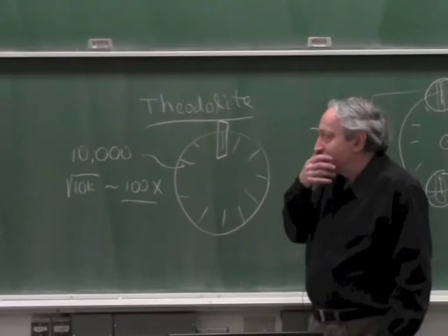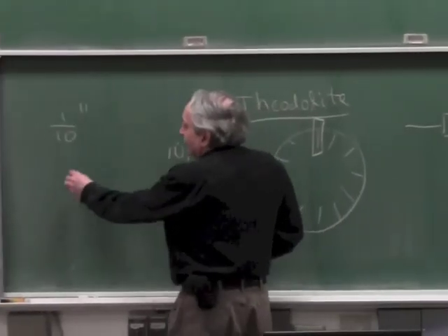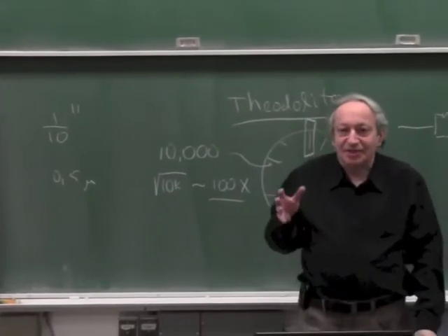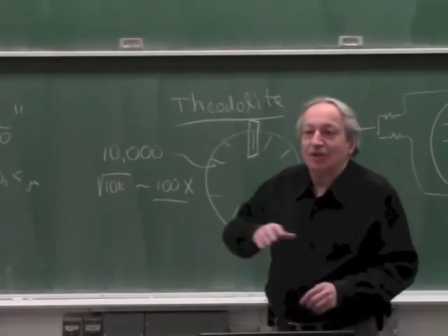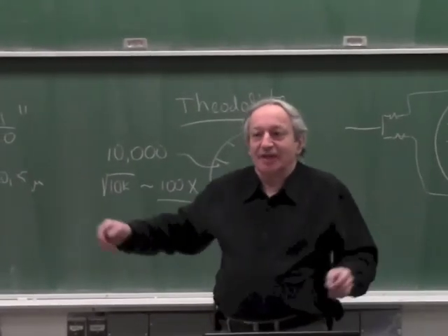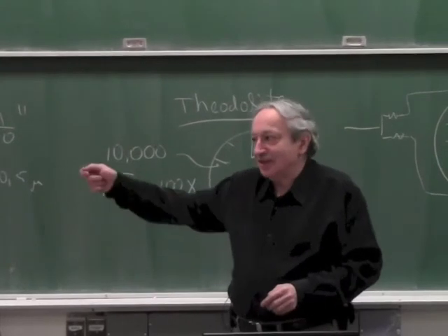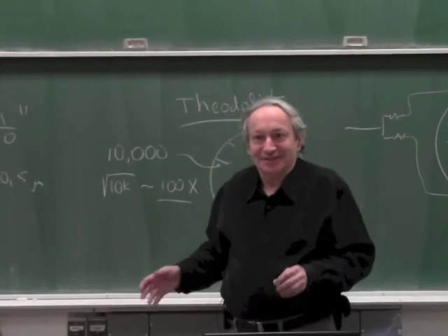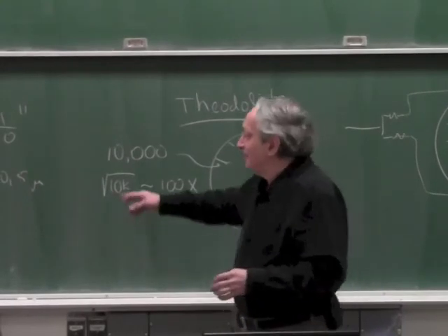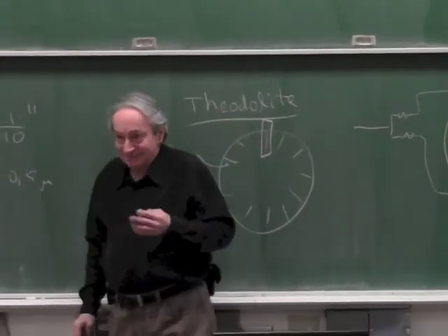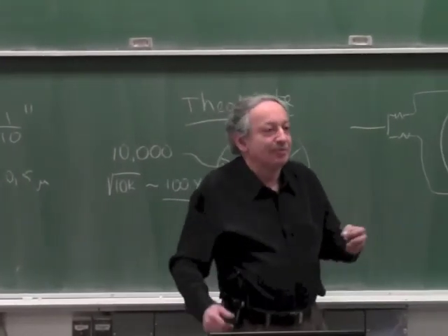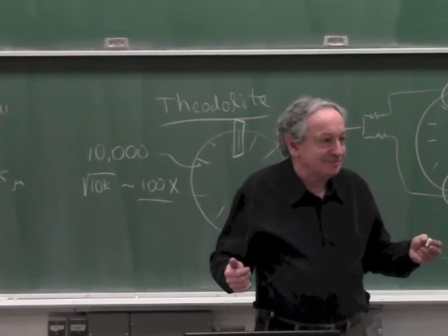That will be 0.5 of a microradian. So it means roughly that if you have a beam 1 kilometer long, and somebody puts a business card under the end of the beam at 1 kilometer, you can detect that it tilted. Just to give you an idea what 1/10 arc-second means. If you calculate, half a microradian is half a millimeter per kilometer.